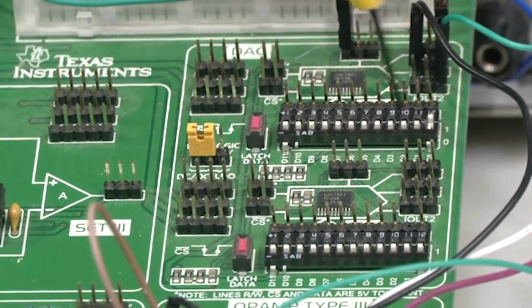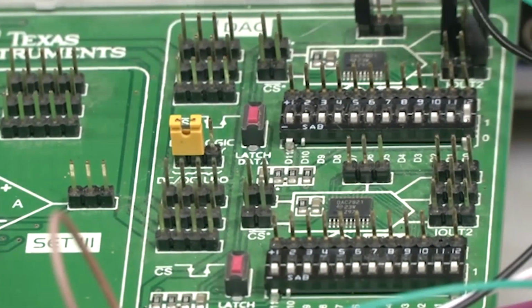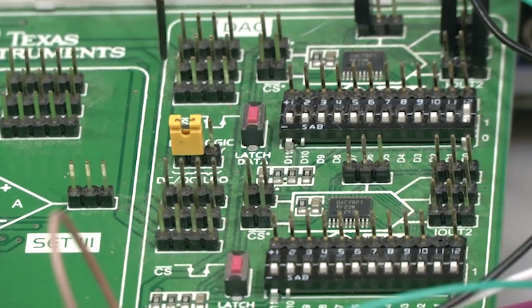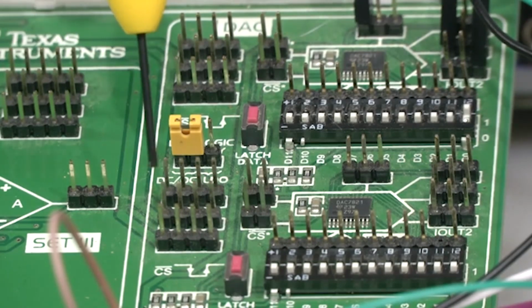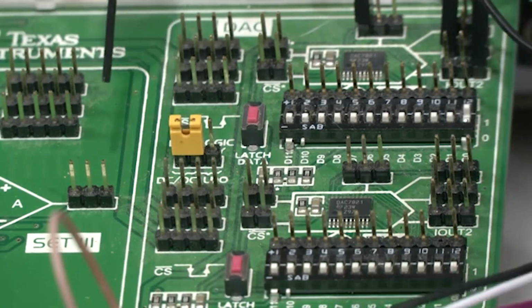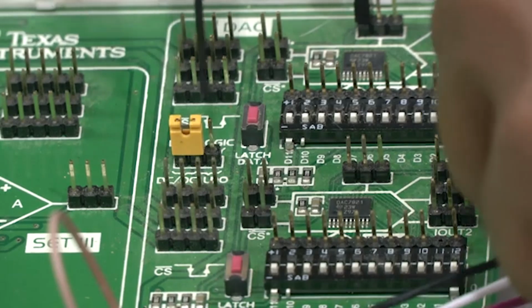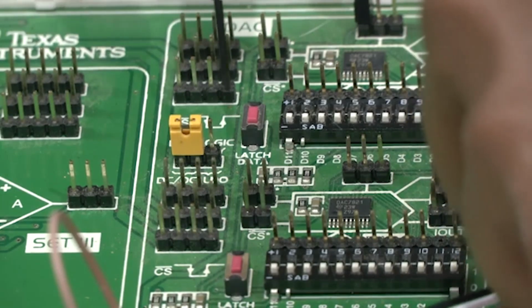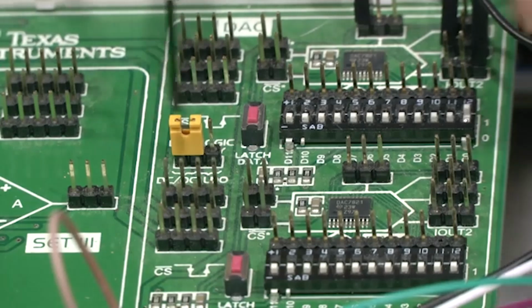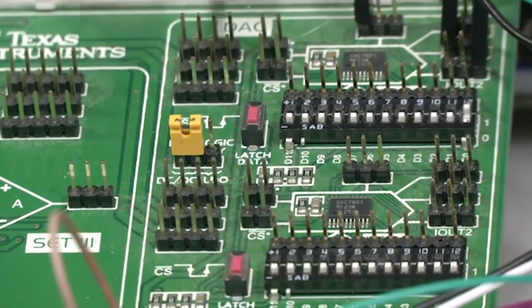So, this is the tri-state switch that is provided for giving the bit sequence. So, from D11 to D0, 12 bit tri-state switch, okay. So, here we can have 0, 1 or a tri-state level to give 1, 0, whatever bit sequence we need, okay. And then we have the supply lines, and there is something called digital logic supply here, which is the logic line supply voltage. This we can give through either the DC voltage or through the low dropout voltage. So, this is DC and you can have a switch selection. So, we have kept the DC level, okay.